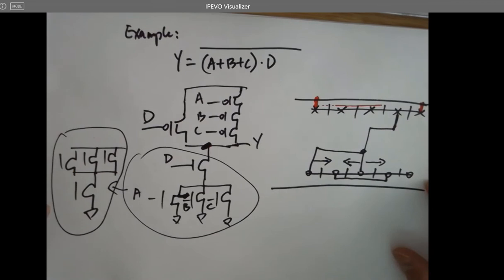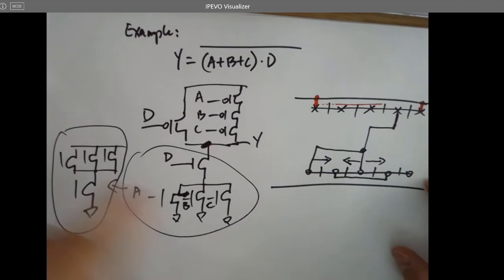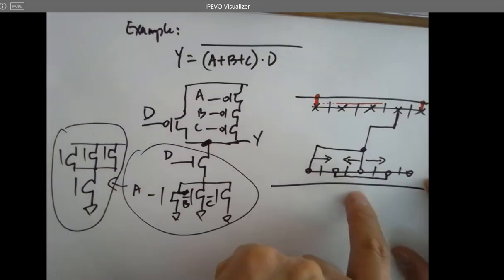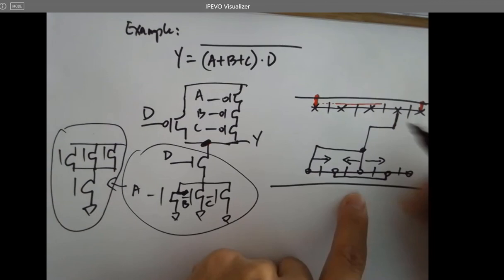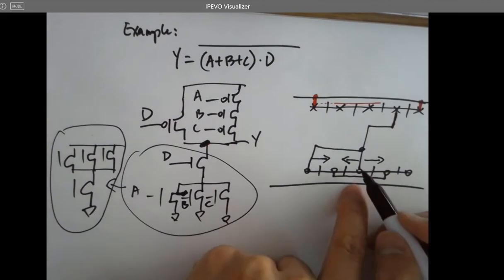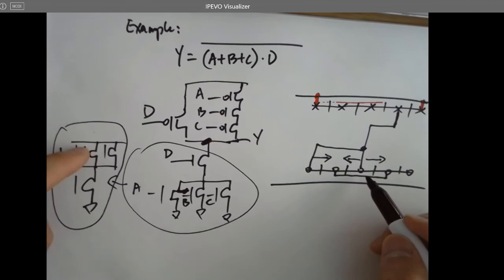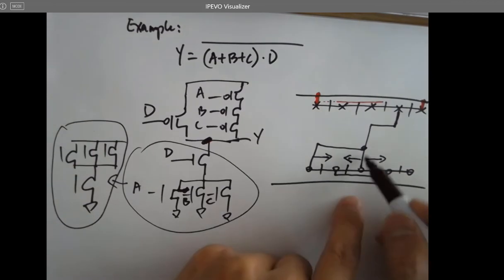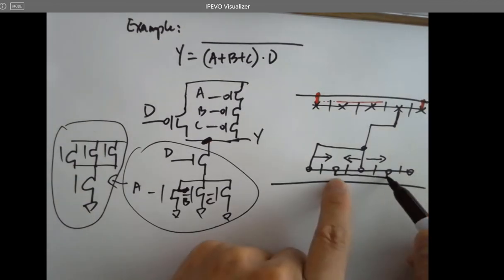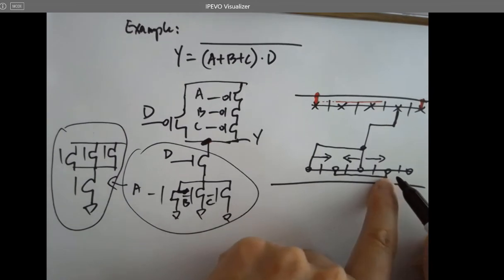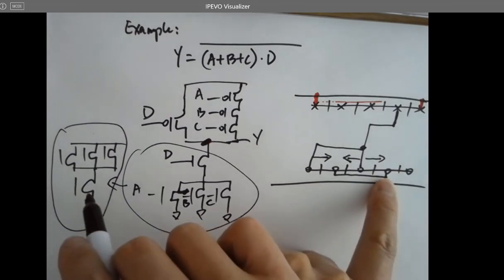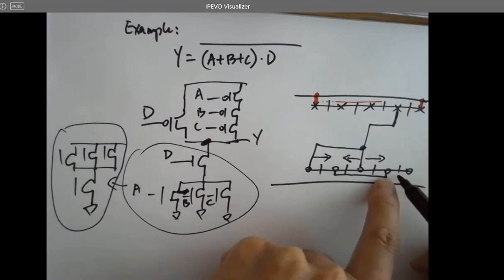If you want to use this one, you have to make the layout like this. You know what I mean? Because the signal comes down here, it's going to meet with these 3 parallel NMOSes first. See here? 1, 2, 3, and merge. So the merged signal is being sent to this single NMOS at the bottom, which is this guy, and ground.